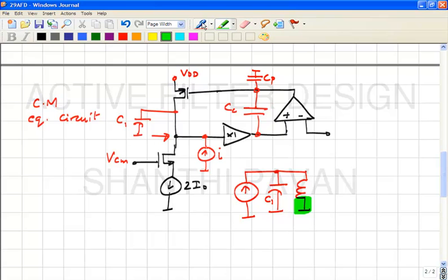A resistor in series with the inductor will also damp a second order network, isn't it? It cannot be in series with the inductor, because we know that at t equal to infinity the output common mode is the same as the initial common mode. So the incremental change in the common mode voltage is 0. Correct? So there cannot be a resistor in series with the inductor.